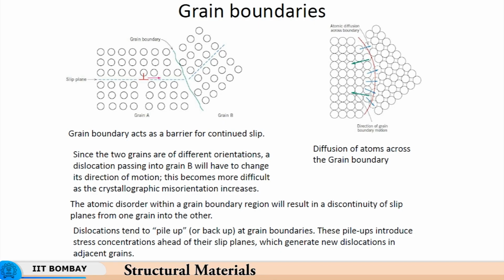That is because you have generated a multiplicity of dislocations by working on the material, by deforming the material, and this multiplicity of dislocations results in an increase in strength of the material. This increase in strength is macroscopically felt as an increase in hardness. And the reason why the material has hardened is because the dislocations have started moving and multiplying.